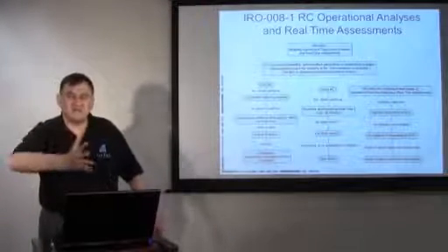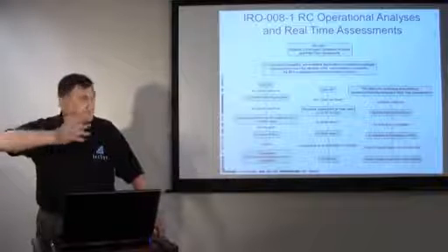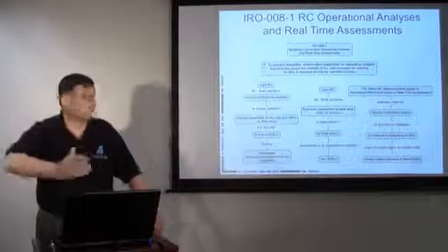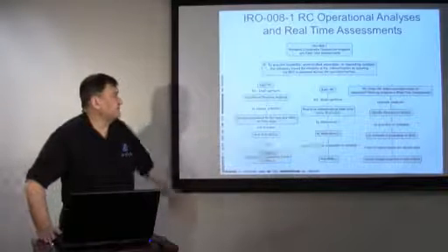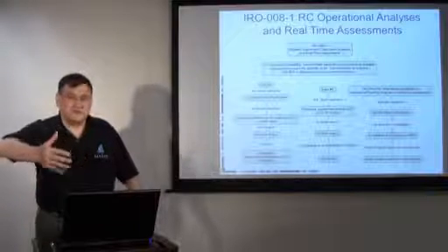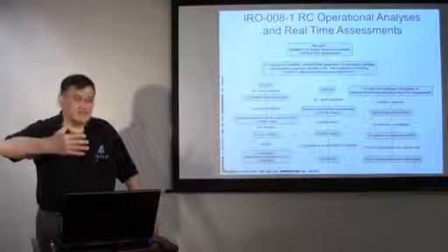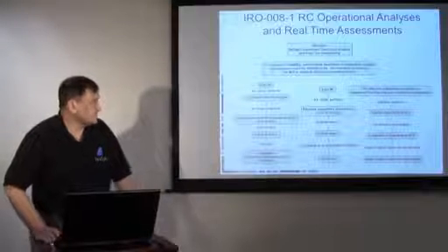You may be running thousands of contingencies. You may have massive parallel computers where you've got hundreds of computers all running different contingencies to make sure you can get it done within that 30-minute period. And then those programs have to boil the results down to summarize the key ones that cause the violations, so you can give that your attention.